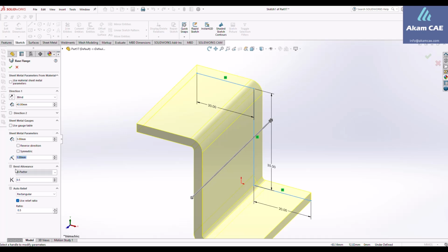And the next thing is the bend allowance, sorry, which shows you the K factor. Here, consider that my material is soft aluminum. For soft aluminum, usually fabricators go with 0.33 or 0.36. It's going to be different from fabricator to fabricator, but normally I put it as 0.33.